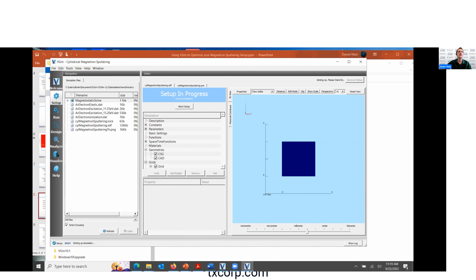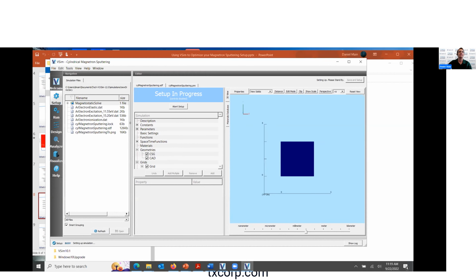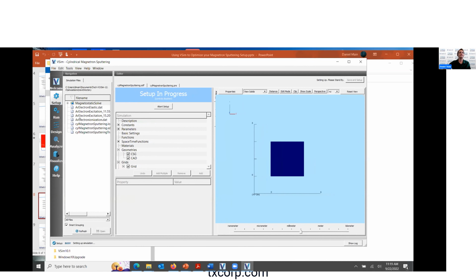We have a cross-section table between argon and electrons, and then we have some excitation cross-section tables, and then there's an ionization cross-section table. I typically use LXCAT to get my cross-section tables, but if you need help with that, I'm more than happy to help you find your cross-section tables for your problem. We also have this external magnetic field, which we are supplying for this problem.